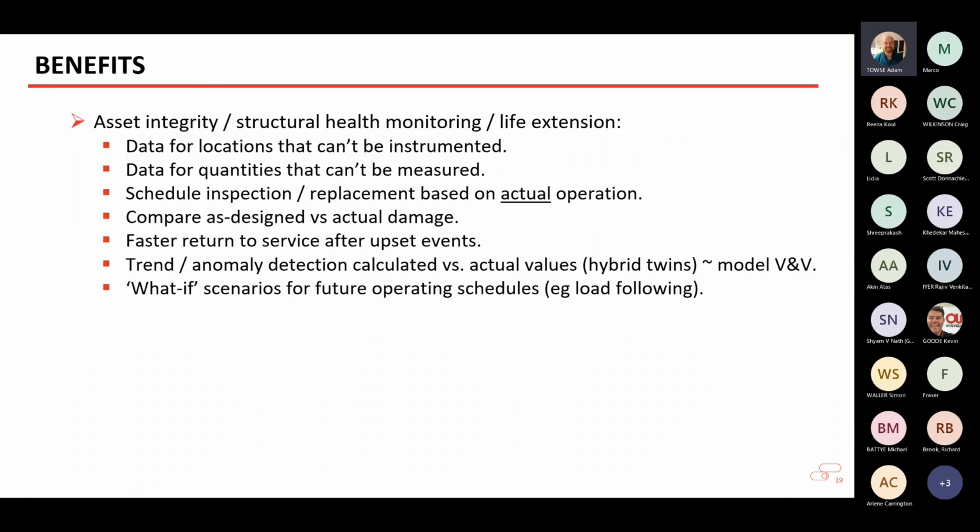And of course, we could have multiple digital twins running in parallel. For safety's sake, I might decide to run one model through with the actual accelerations that just occurred, and then another model through with that acceleration trace scaled up slightly, and maybe a third model where we'd assume that there was a bit of corrosion or thinning on some of the pipe work. Because you're not really limited other than by software and hardware resources, I can have as many twins running in parallel as I want.